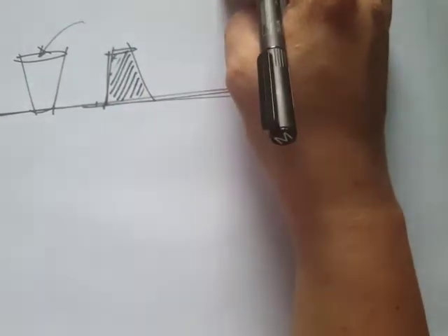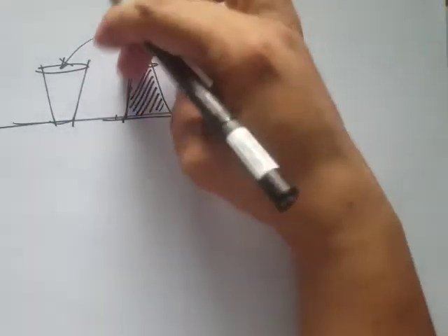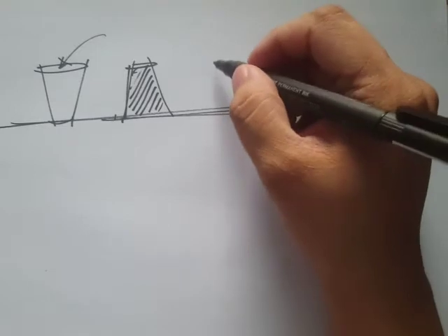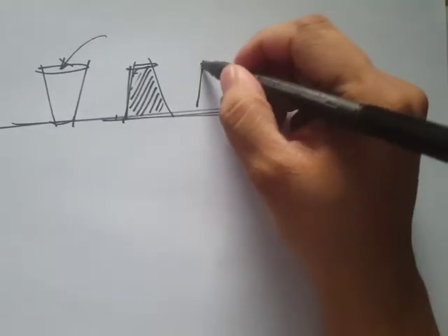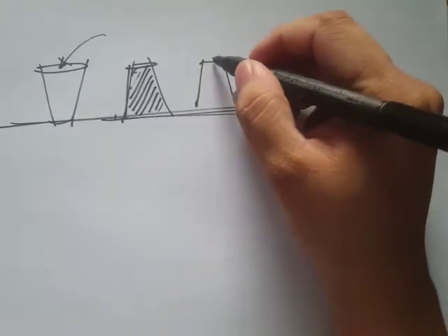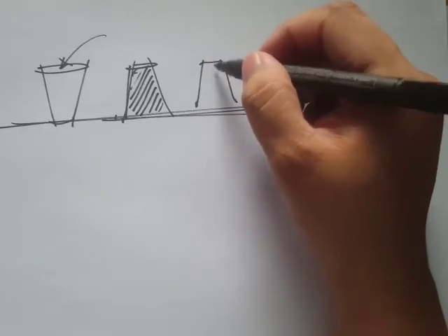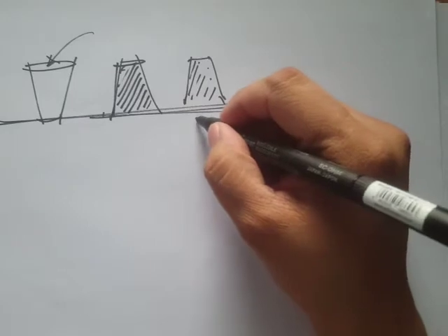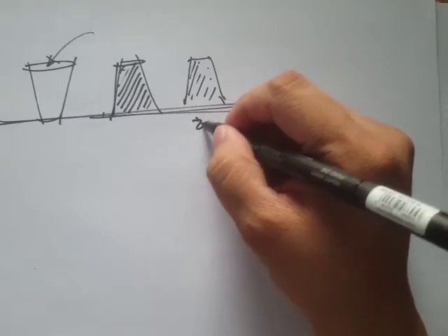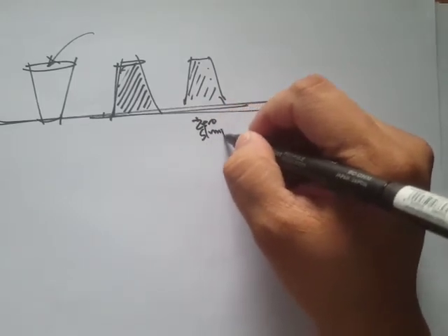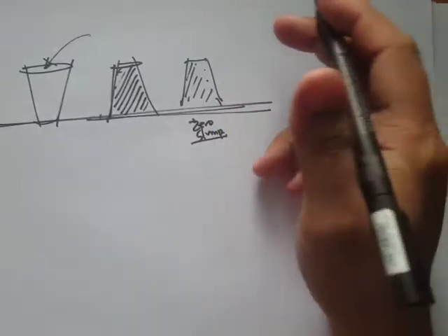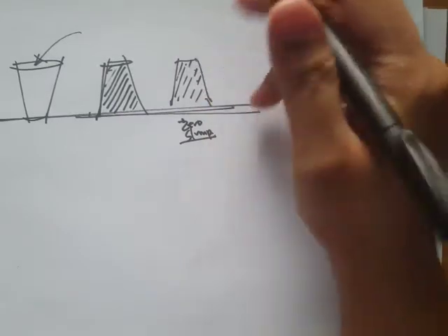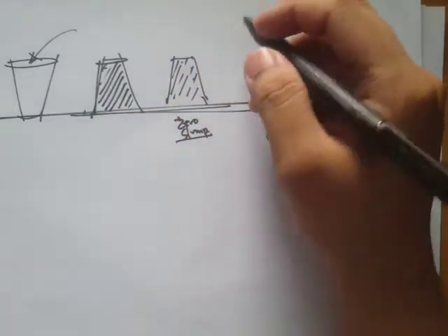Okay, so let's say we have this, it's already filled with mix. Once we try to remove the mold, what will happen to the slump? If the slump remains the same, I mean did not decrease in height, then that's what we call true. Oh no, that's not true. That's a zero slump. So probably you get less water, so that's not what we wanted.